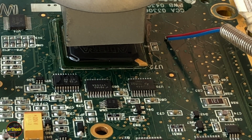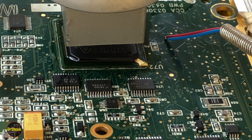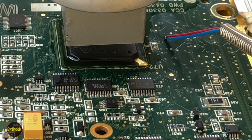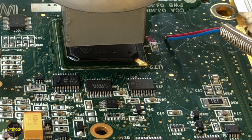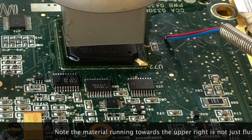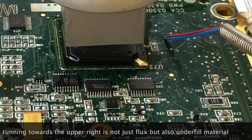All right, the board temperature stabilized. We're going to turn our hot air station on now, and we're going to bring it up the rest of the way to the melting temperature of the no-lead solder that was originally used by the manufacturer. Try to ramp this up pretty quick here. Currently at 185 degrees and climbing.